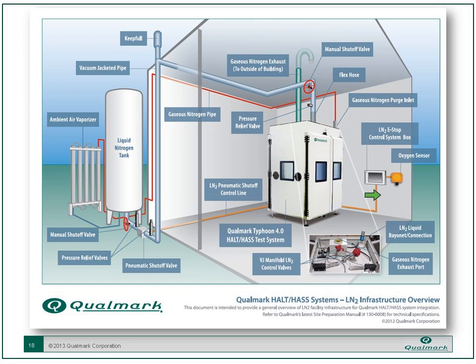Nitrogen itself, of course, isn't dangerous. 80% of what we breathe is nitrogen, and it's only a problem when 100% of what we're breathing is nitrogen. And that's what the oxygen alarm is for, in case there's a spill or a leak and you have an oxygen depletion situation. And this also just gives you a schematic of how the liquid nitrogen is controlled by our system on the top of the chamber.